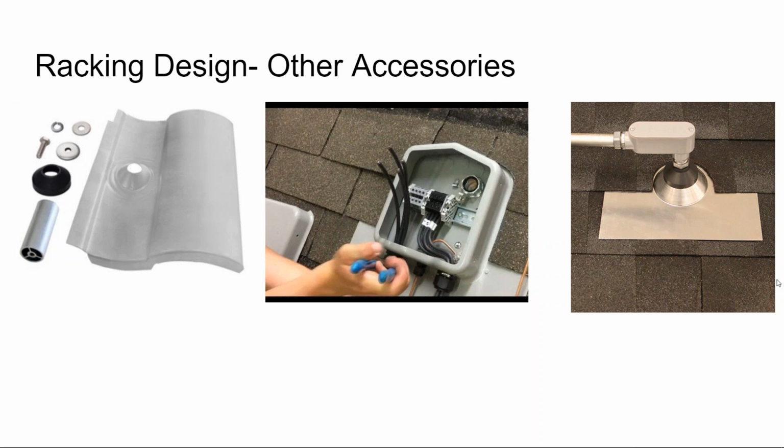You don't have to worry about that when you're lagging into the rafter through the roof, but if you're just kind of sticking the array on top of the roof and not doing anything but clipping it, you need to be more concerned about how the existing roof is attached to the rafter, since you're not yourself positively attaching to the rafter.